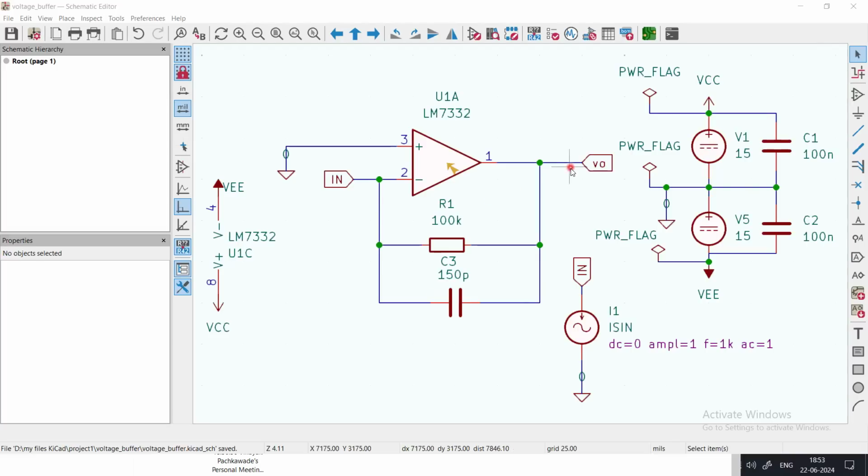Output of this circuit is fed directly to the analog to digital converter on the PCB when you are doing a complete electronic system. So besides that, this current to voltage converter or trans impedance amplifier has a variety of applications. Now why I have used LM7332, because it provides me a wide range of input and output. We have used the same part in our previous model also, so it is not necessary you should use this part. You can choose the part suitable to your application.